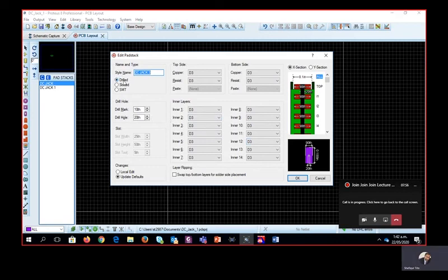Now from here, this is the drilled, and we need to make it rectangular. So we will select the slotted one. And the width here, we have to keep the actual width of that slot. So that was 40. And we have the slot height that was 138.